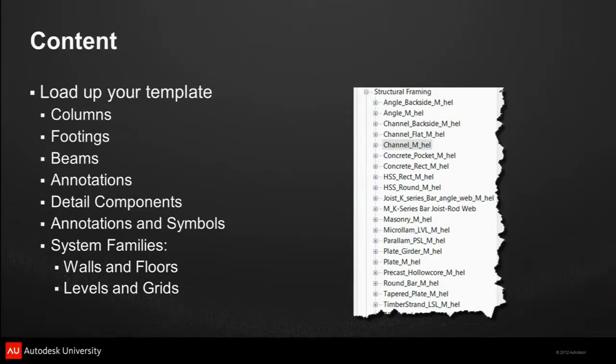Why do I do this? Once again, 24 offices. If they're to come into this template and they need a beam, there's what the beam is named. If they go onto this beam, they select the type, reload, it takes it right to the company standard content. So, how many people use reload from the browser? Yeah. So it's just a method to keep everything consistent. They don't have to go looking for the content. Hit reload. Comes right in.